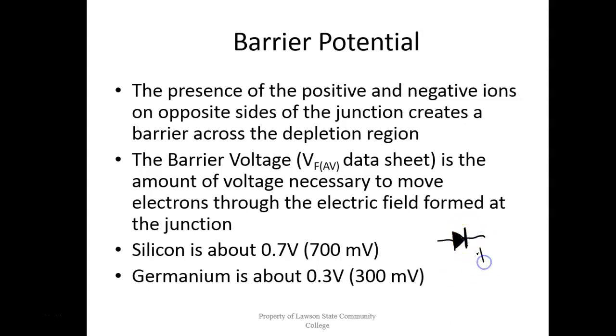So what that is, this is indicating the N side, and then this right here would be indicating the P side. So then the actual device itself, the one I passed around was black, so mine's going to be opposite. We have that line that goes around here, and so this lead right here would be the N side, this lead right here would be the P side.